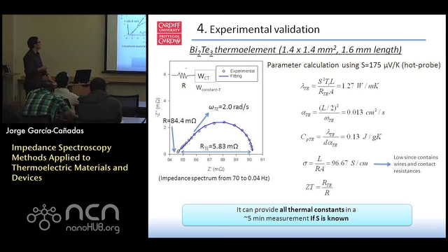And then I connect this more or less simple setup to my potentiostat or impedance analyzer. So these are the results of a bismuth telluride element. These are the geometry and the length. And you will see the response is very similar to the one predicted. And also if you use the fitting to resistance in series with a heat-sink Warburg, from the fitting you have the 3 parameters: resistance, thermoelectric resistance at the characteristic frequency of thermal diffusion.